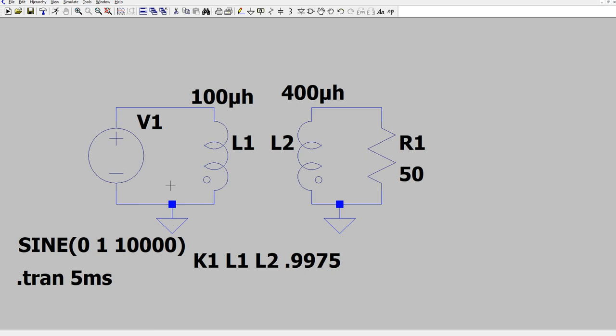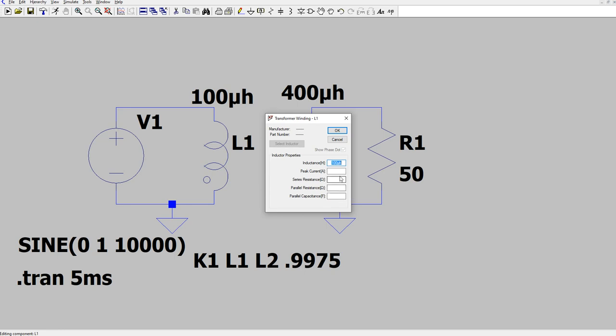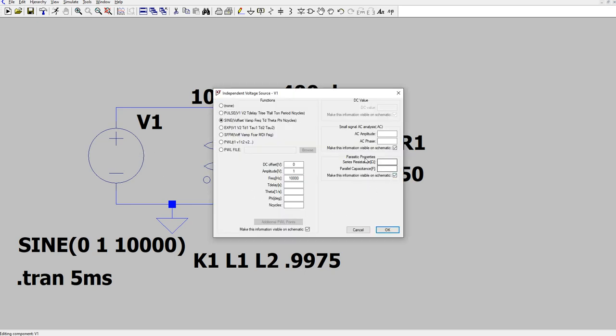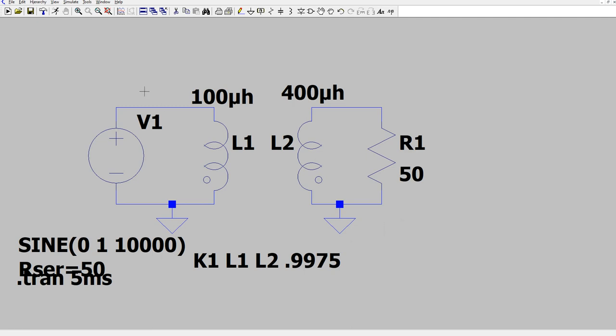And the easy way to do that is either to add a little resistance here with some series resistance, or to give the generator a source resistance, which let's just make this a 50 ohm generator. And now everything should be happy. Okay, now remember that we have a 50 ohm source here. Let me move that R serial parameter so it's not overlapped.